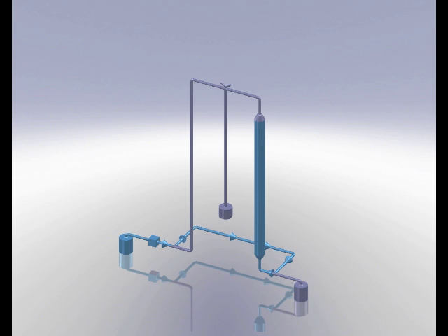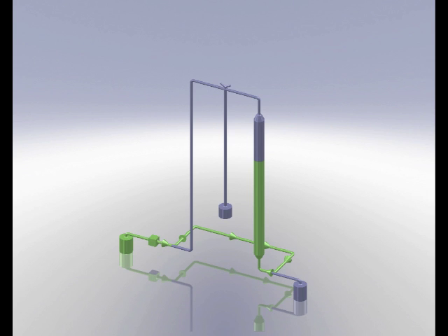One of the advantages of using the separable mixed bed resin we chose is that the bed may be regenerated upon exhaustion without cross-contamination and without disposing of resin, which can be very costly. The specific gravity of the anion resin is 1.07, and the specific gravity of the cation resin is 1.27. This means that when the bed classifies, the anion and cation resins will separate. In this manner, regenerative chemicals may be applied separately.